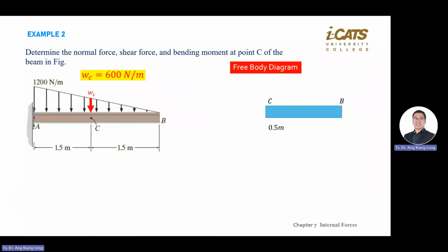My explanation is at A you have a very high number here, 1,200, and you also need to solve for unknowns at A. If I only take the B and C section, there is no support, so I don't need to find A. It's a smarter way of doing things. Of course, if you want to include this section also can, but you're asking for trouble.